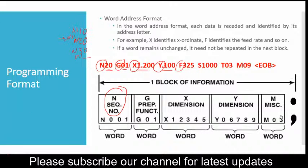So it is advisable to keep a space of 10, 20, 30 in between. If the number is preceded by N, it is interpreted by the machine as the sequence number. It is the sequence by which the machine will read and operate the program.